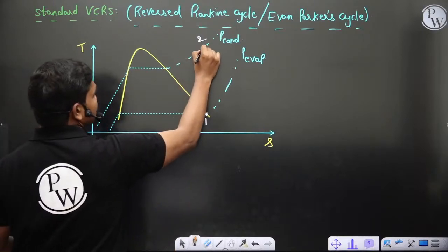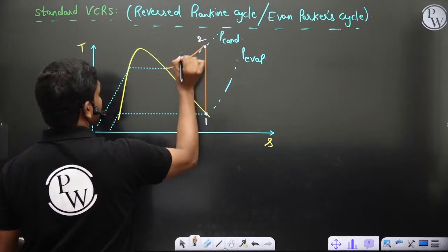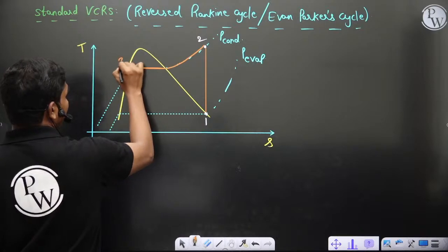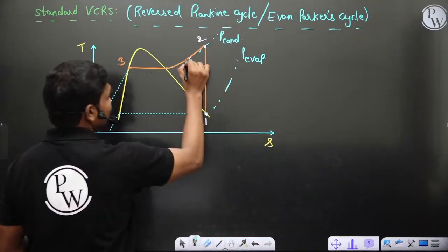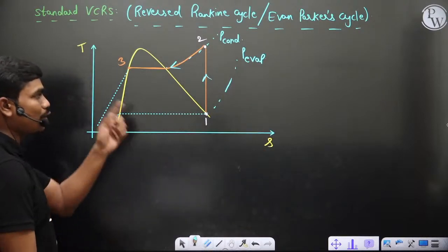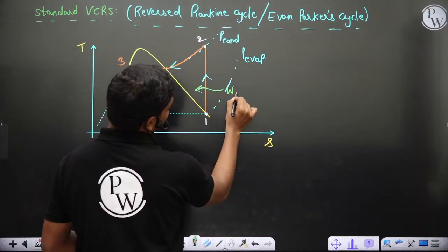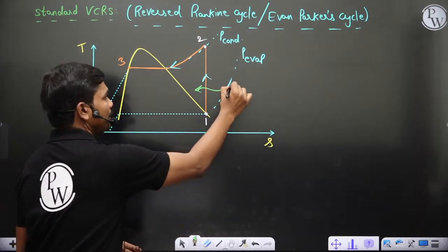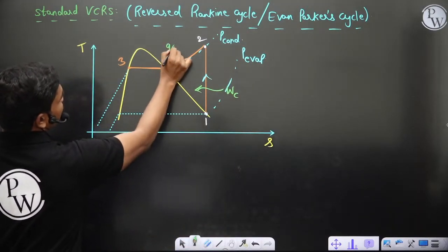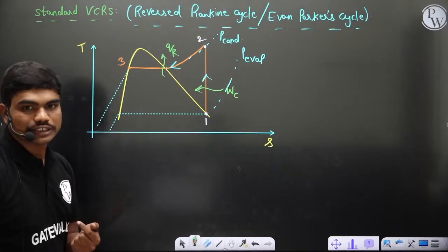So in the condenser, at condenser operating pressure, we will do this heat rejection from 2 to 3 at constant pressure. So 2 to 3 is the constant pressure heat rejection. 1 to 2 is compression, where with the help of some compressor work input W_C, or W dot, or specific work if you take specific quantities, you will be able to do this. Then this heat rejection happens as Q_H, or Q ejected, Q_R let us say here. So that's Q ejected.